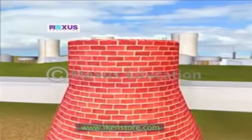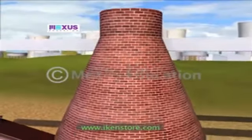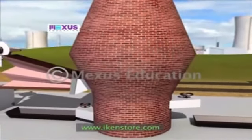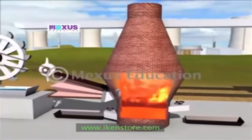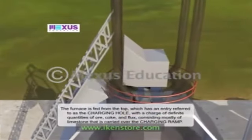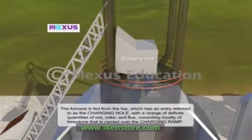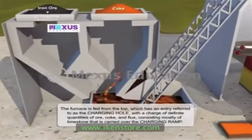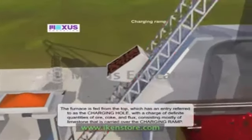Lined with fire brick, the furnace is narrow at the top, increasing in diameter downward, but narrowing again suddenly almost at the bottom to form the hearth or crucible where the fine molten products are caught. The furnace is fed from the top, which has an entry referred to as the charging hole, with a charge of definite quantities of ore, coke and flux, consisting mostly of limestone, that is carried over the charging ramp.